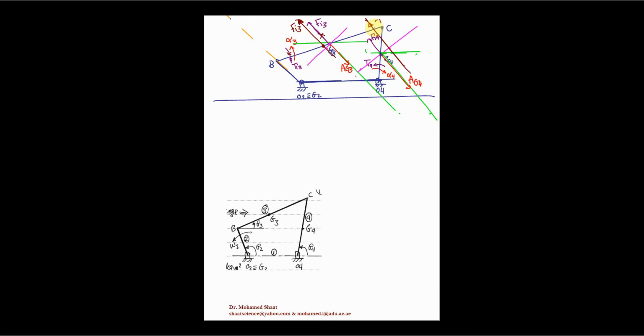Make sense? We have to locate the point of intersection of this new force with link number 4, because we're gonna need it. Then we can cancel this force and this torque as well. So we're just gonna end up with one force acting on link number 4, as already given here.